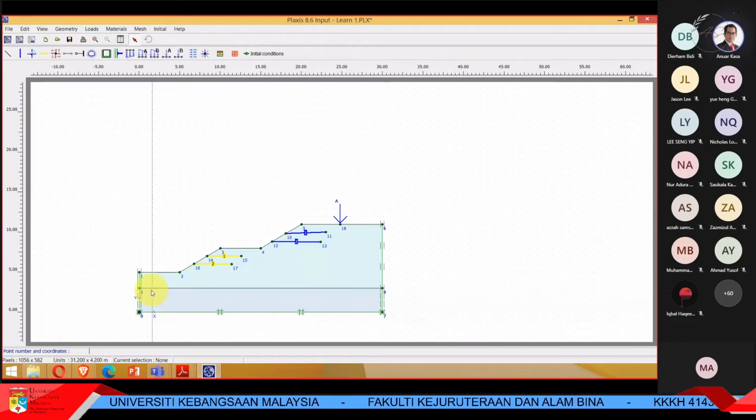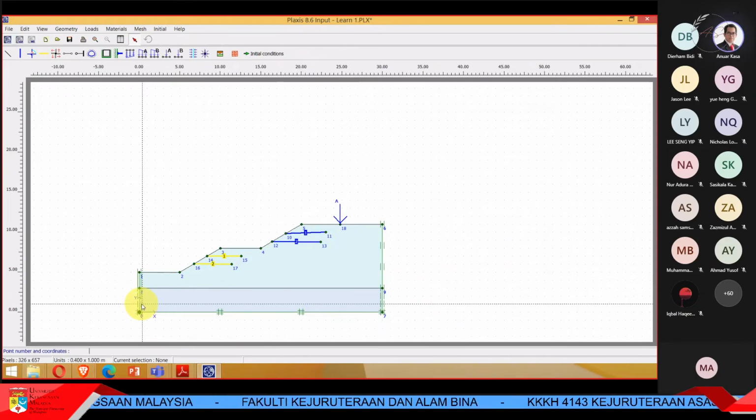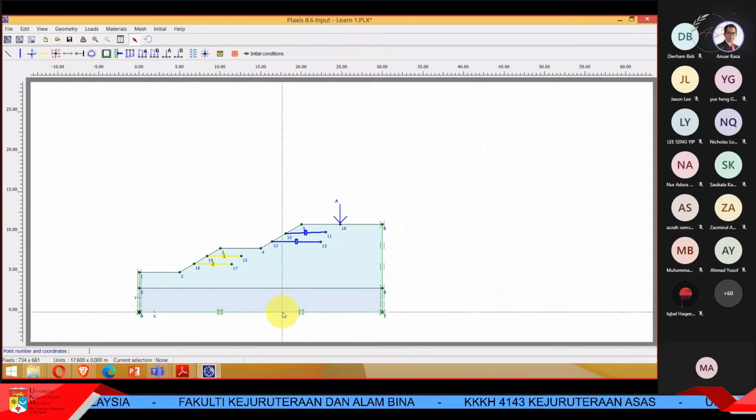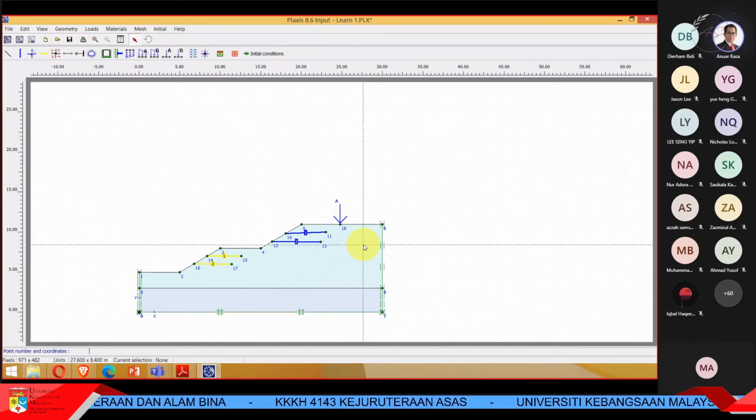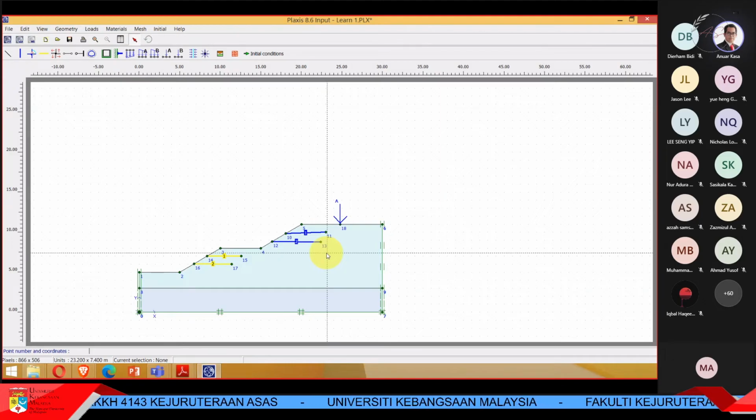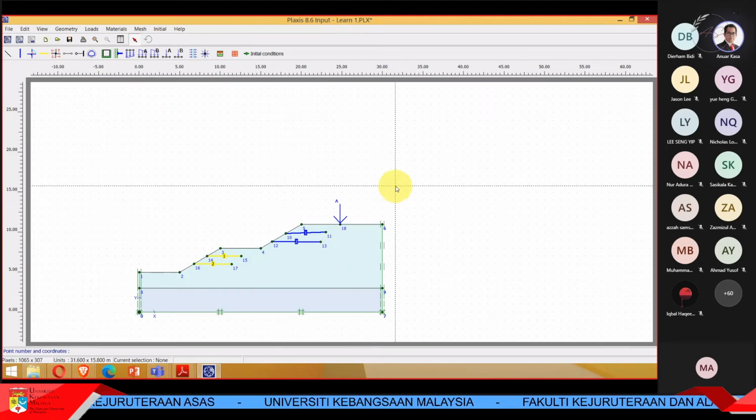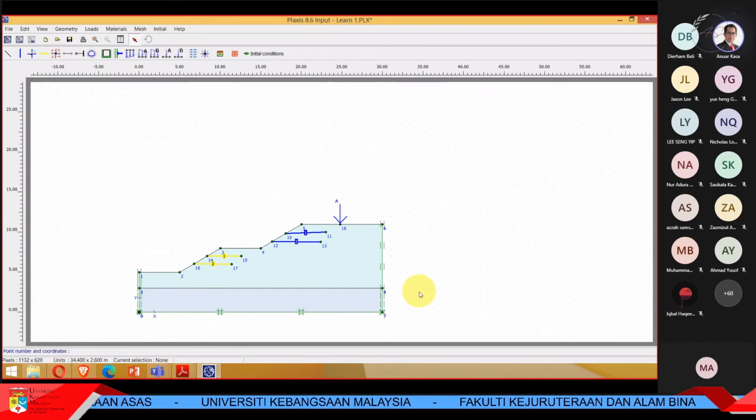To check the water pressure, you know this height times 9.8 or 10. So you get the value of water pressure. You check with Flux, is it the same? Simple checking. The rest, I don't expect you to check because finite element is a very tedious, long calculation if you want to do it manually. And I think you are also not equipped with that. It is at the postgrad level. I hope that answers your question.